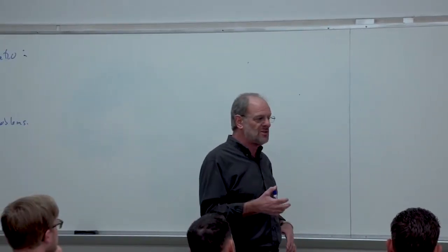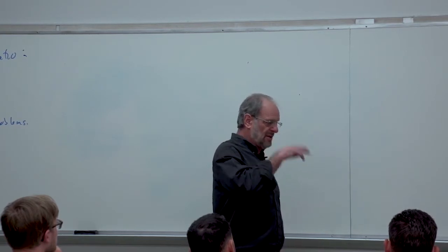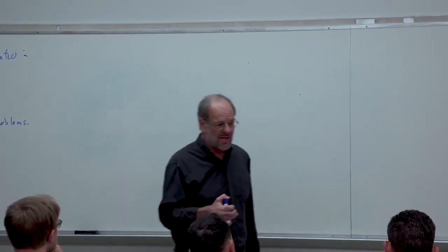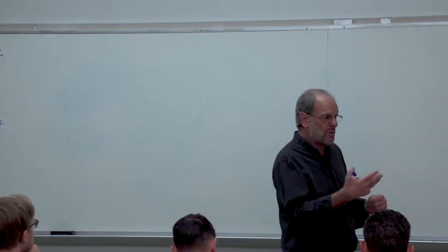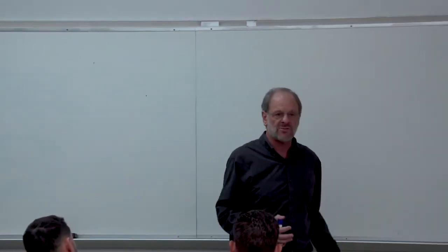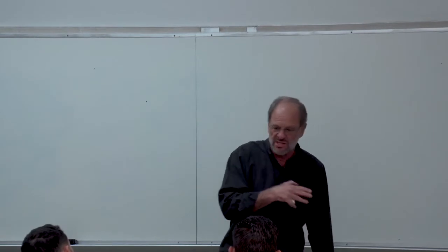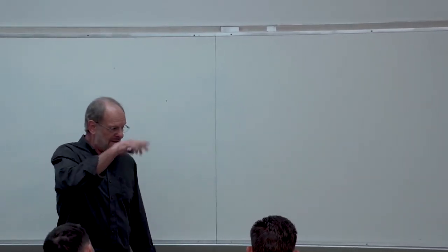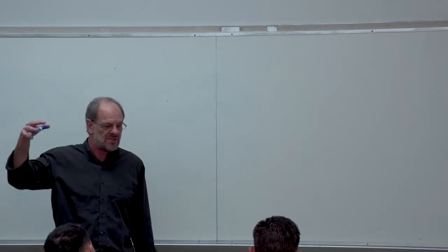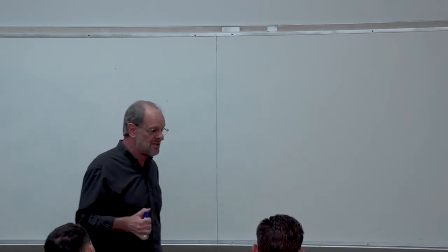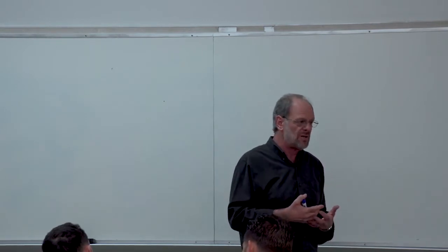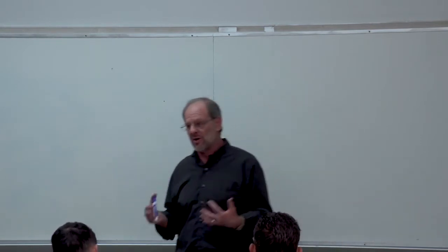And the third thing we can do is look at the turbine and ask ourselves, is there some way we could produce work in the turbine that is greater than the amount of work we would see from the simple cycle? And again, the answer is yes, and it's really for the same reasons as we looked at minimizing compressor work by compressing in stages. It turns out if you expand in multiple turbine stages, then you can also maximize the amount of work output in that turbine. So we're going to look at all three of those things.